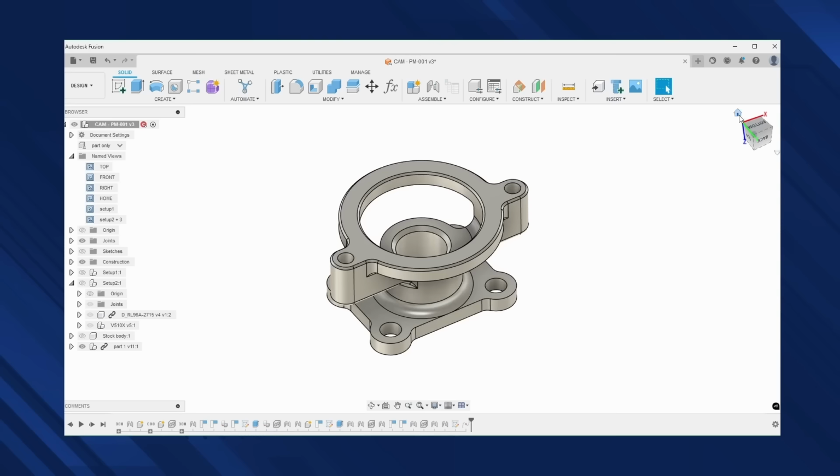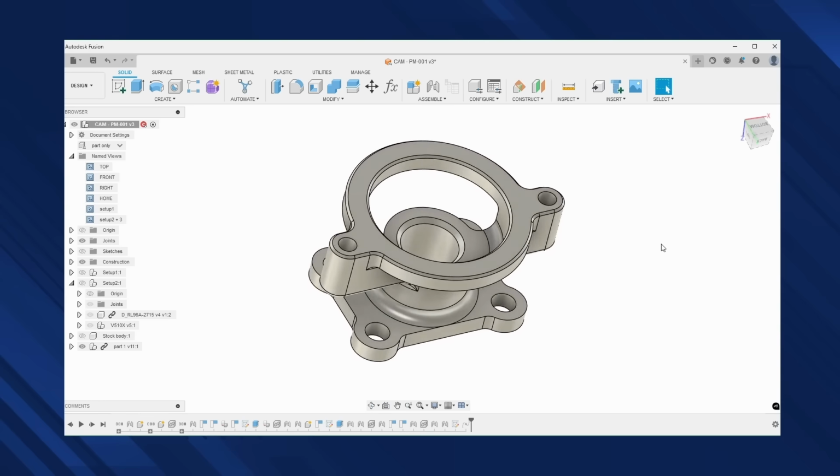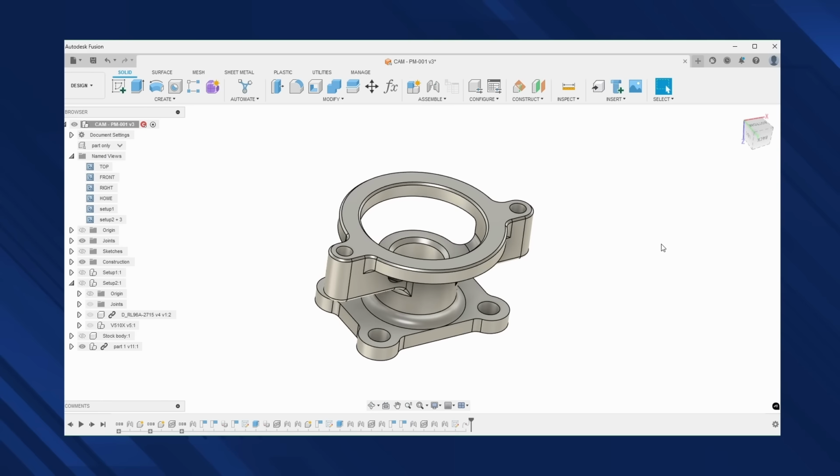In that case, you end up with parts sitting on a cart idle when they could have been finished in an hour or two. But let's get back to the part. I'll orient the part with this face side up in Op1 so I can flip it around and sink it into a soft jaw for Op2. Now that we have a manufacturing plan in place, we can bring this part into an assembly with our vises and begin designing the soft jaws.